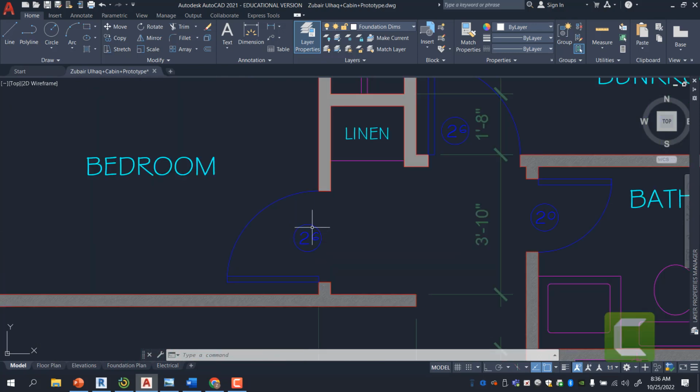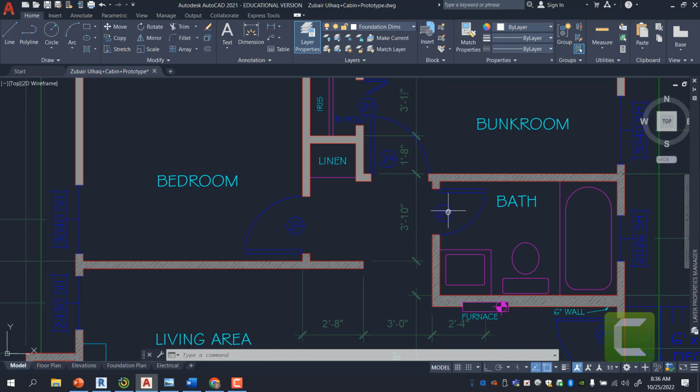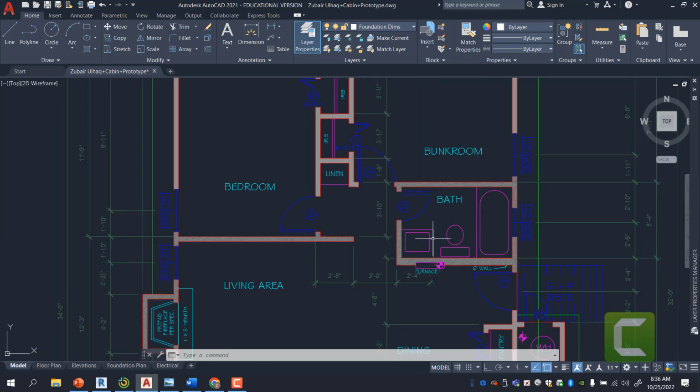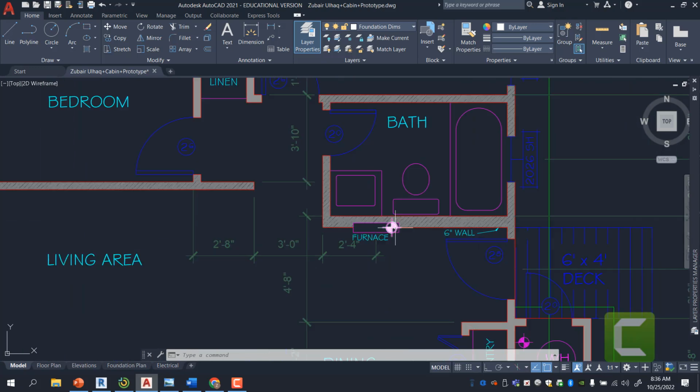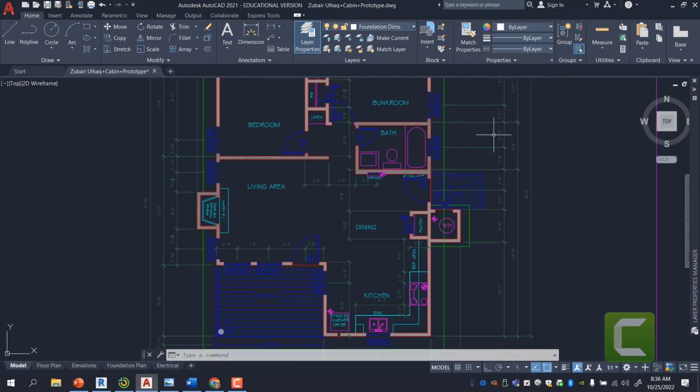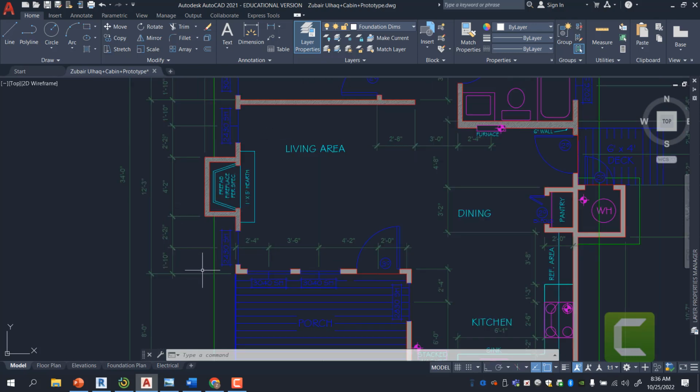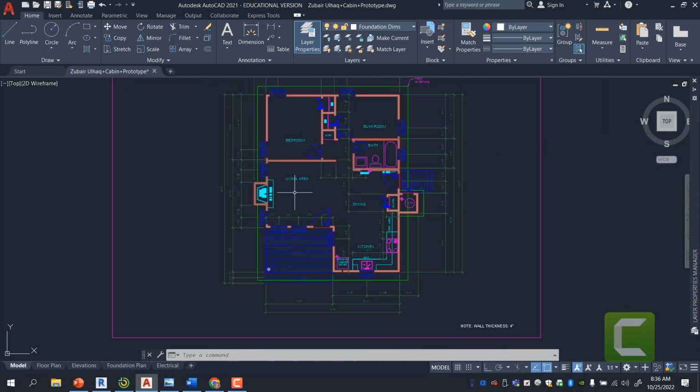Now when it comes to doors, these doors are interior 2 foot 6 inch doors. That's a 2 foot door. And that's what I want you to read this as. You place your fixtures. For example, there should be a dimension line that measures to the middle of this fixture, middle of the toilet, middle of the tub, and the clearance of 5 feet that goes from here to here, indicating that there is a space for a bathtub. So when you're dimensioning, you have to make sure that you're catching every one of the walls.